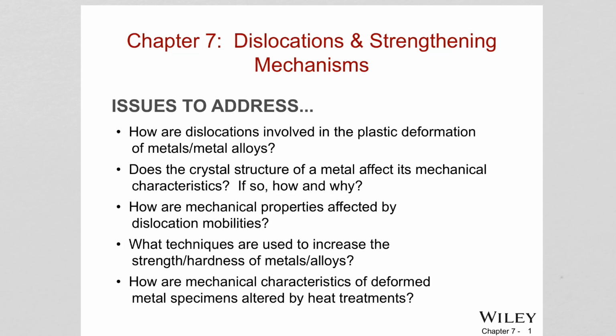like if it's BCC, FCC, HCP, is there a difference in behavior depending on the crystal structure, and if there is, then why? And then dislocation motion affects all kinds of mechanical properties, not only strength. So we're gonna learn this relationship between dislocation motion and mechanical properties.